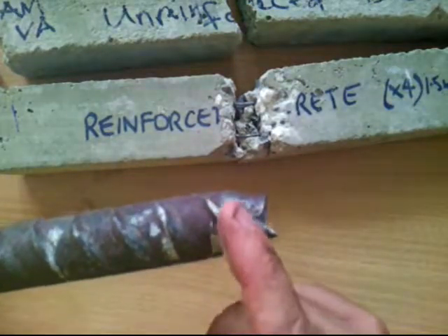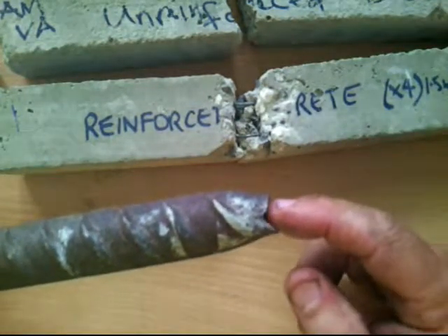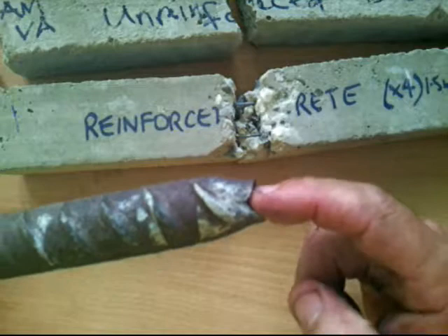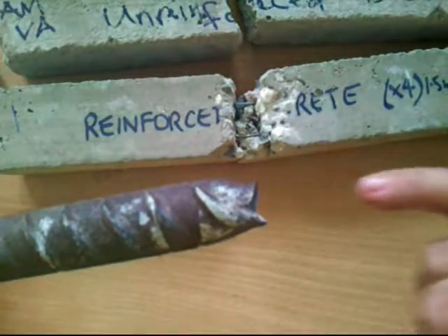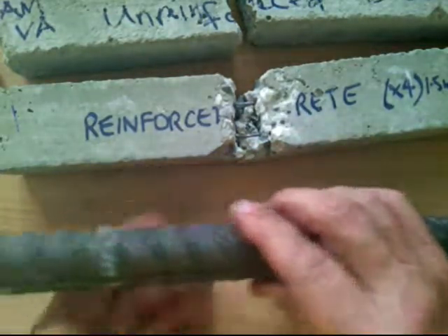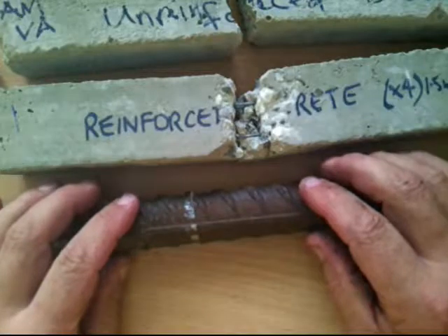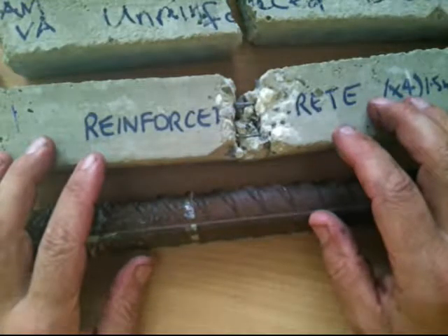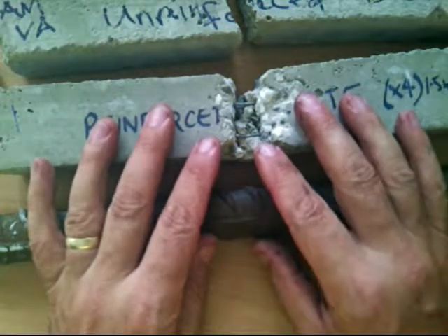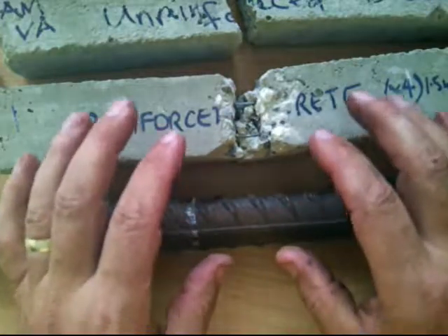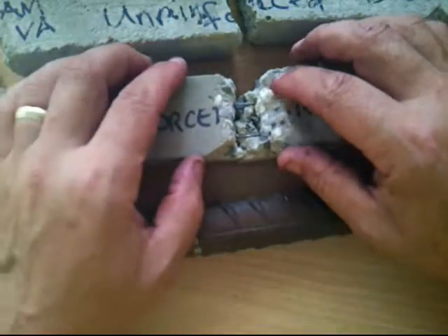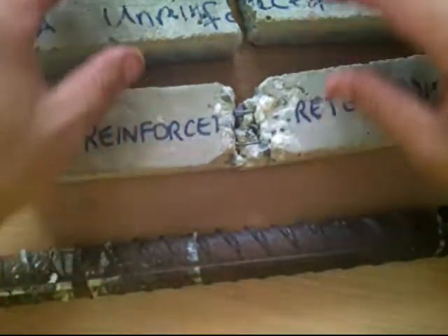And in this case, very interestingly, at the end of this rebar, you can see that it's necked, and it's been under a lot of tension, and it's finally fractured in a ductile fracture, where you've got that cup here, and then there would have been a corresponding cone on the other bit of rebar when it failed. It's been put under a lot of stress. Okay, so reinforcement, steel reinforcing, creates a change in the original material of concrete, and a mixture of the properties are applied, and we can customize the properties of objects by using composite materials and joining them together with other materials.